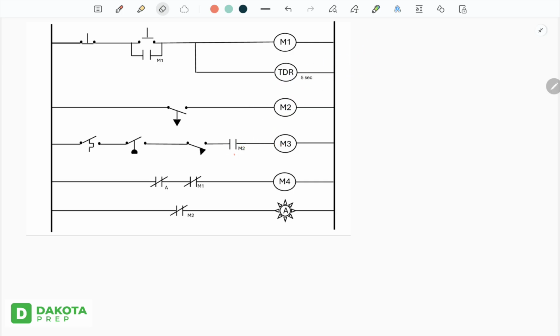All right, so let's move on, make it a little bit harder. Let's change this guy. I think I've only got like 2 colors here. Oh, that's a terrible color. Let's get rid of that. Let's keep using red. Let's change this guy to an on delay. So now it's going to close when this one turns on, when this is energized. We'll still stick with M3.